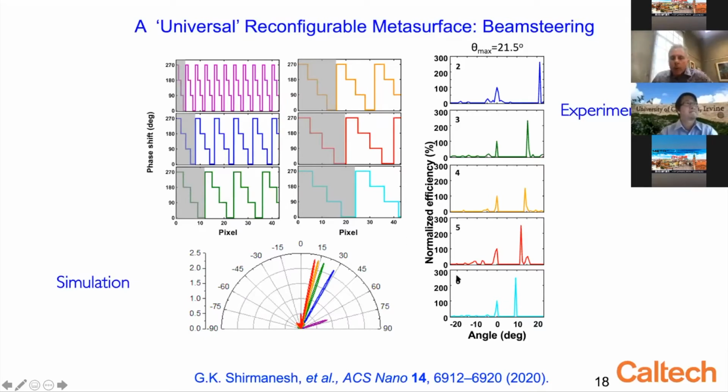In experiments, what I find is I am able to steer a highly directed beam. There are also some undesirable artifacts where power is steered in sidebands that was not intended. For example, you can see there's some power steered at the specular beam position and a little bit of power off at negative angles here, whereas the steered beam is being steered at between about 9 and 21 degrees at positive angles. So I'll show how we can mitigate this with inverse design in a moment.